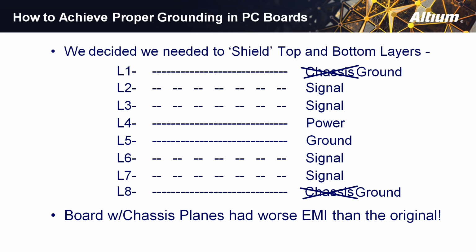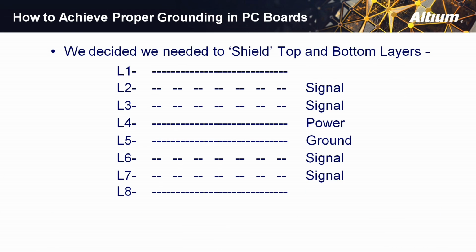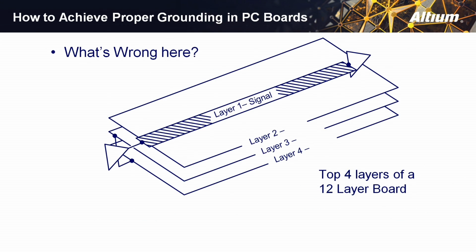It wasn't until many years later, dealing with the automotive world and their 4-layer boards that were signal plane, that I finally realized why this was a problem. You can't do this. Having a board that has 2 signal layers above a plane on layers 1 and 2 of the board. Now, if the dielectrics are really, really thin, as they would be in an HDI board, you might be able to get away with that. But with thicker dielectrics, as in a 4-layer board or a 6-layer board, really, really a bad plan. And that's the issue there.